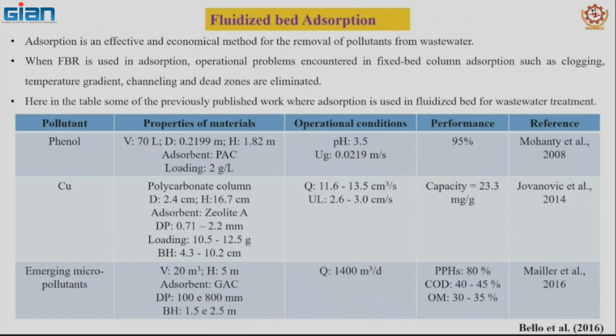So among these three types of application of fluidized bed bioreactor in wastewater treatment, let me first discuss the fluidized bed adsorption. As we know, adsorption is an effective and economical method for the removal of pollutants from wastewater. This is the most widely used treatment technique. Every household is having one adsorption unit. The water purifiers we are having, a carbon bed is there.